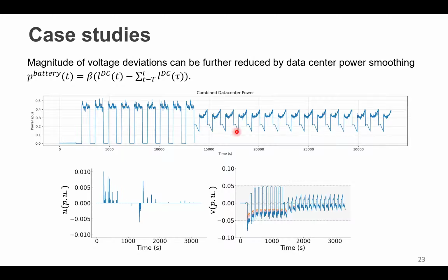We're trying to understand. Yeah, totally agree. These are all excellent questions. You should read my paper. The question is about the modeling of the voltage control problem, right? So what is the right modeling? First, in terms of the R and X matrices, for the distribution system, the R and X matrices come from the actual resistance and reactance of the power lines, and how sensitive the voltage is to active power or reactive power.